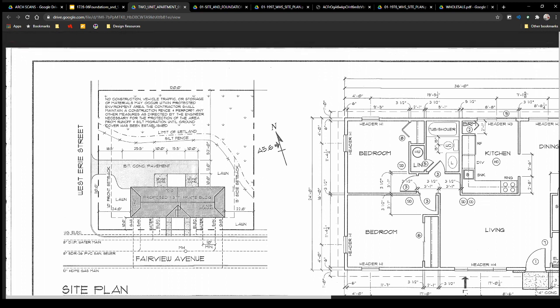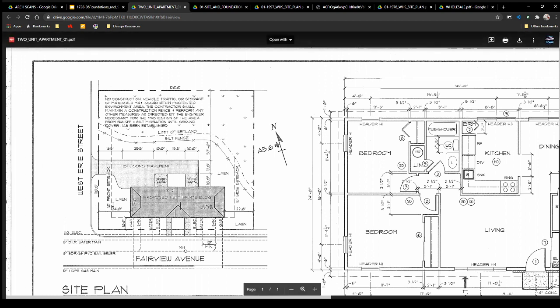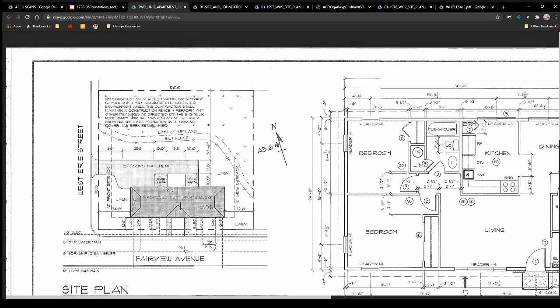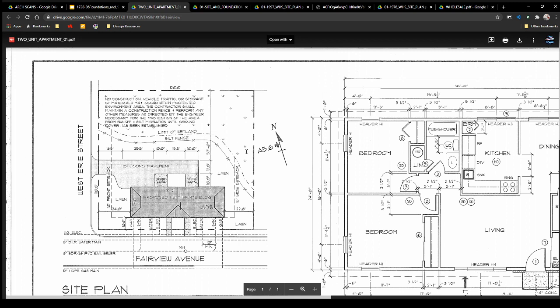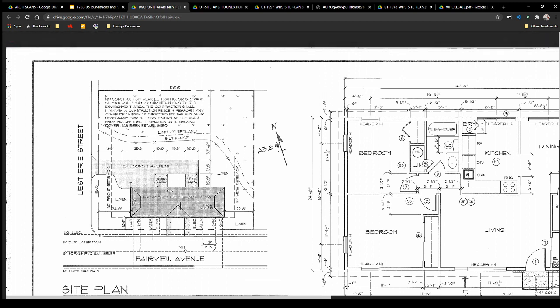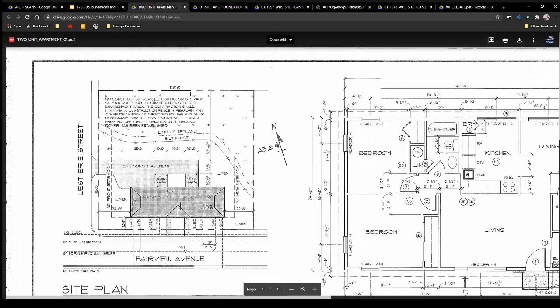So on this side, we have to be 15 feet away from the property line. On this side, it looks like 10 feet away. On this side, 10 feet away. And in this particular instance, there's a wetland area here that also no building is permitted in. So even though all of this property is part of what you've purchased, you only are allowed to build in this area.